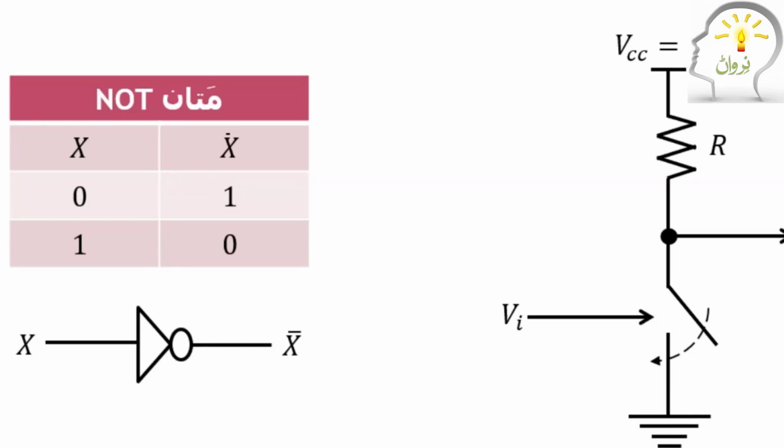Okay, now if you close the switch, then what will happen? Then current will flow through the resistance. What will the output be? Output will be 0 because there is no obstruction between this node and the ground. So this gets connected directly to the ground, so V naught becomes 0. The value of R2 is 0 because when the switch closes, resistance becomes 0.